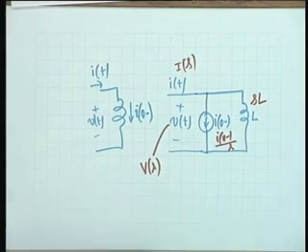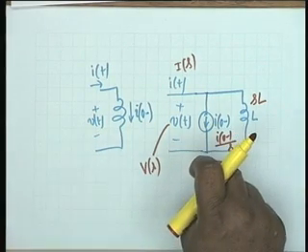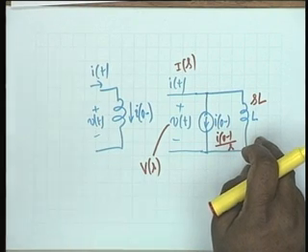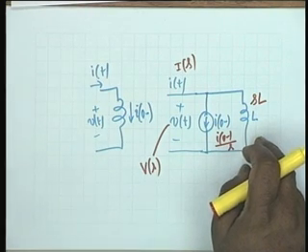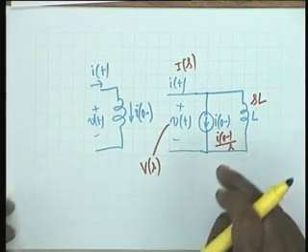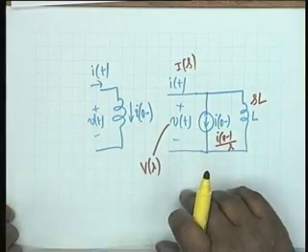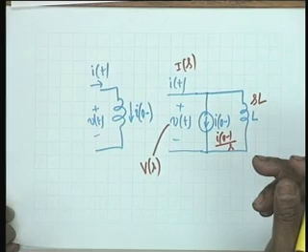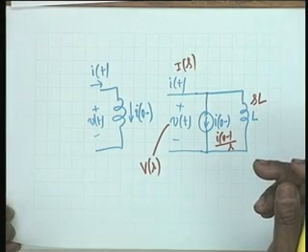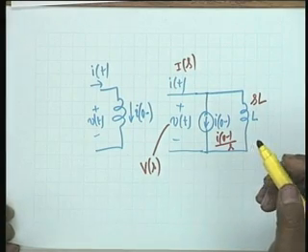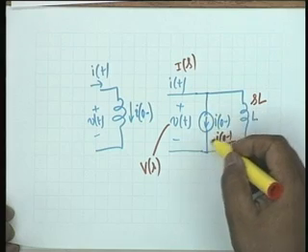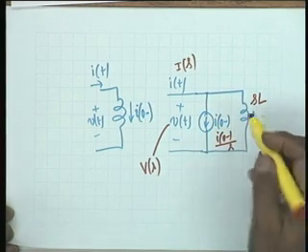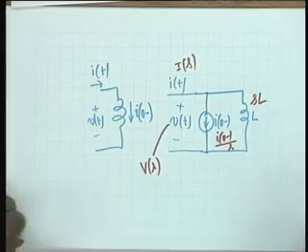Alright. So, in one stroke we have done the time domain equivalent and also the frequency domain equivalent without any approximation, without any loss of generality. I can represent an inductor carrying an initial current either in the time domain or in the frequency domain by means of a parallel circuit, and the parallel circuit consists of an ideal current generator and an inductor which is initially relaxed.